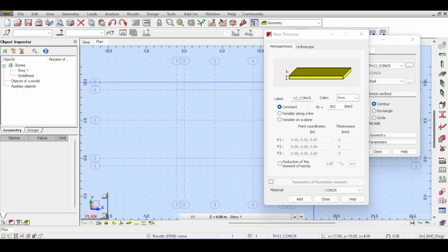An experience I have personally is that for a high-rise building up to 10 stories, we use 100 millimeters per each story, with a minimum of 350 millimeters. Meaning, if you have a 7-story building, I usually start my raft assumption at 700 millimeters. If I have a 9-story building, I usually start my assumption of the raft at 900 millimeters, and so on.